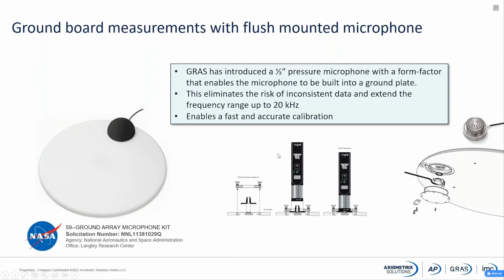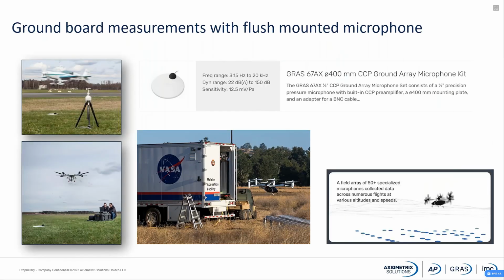What is also a very good advantage is that we have an adapter where you can put it on the microphone directly, and you can do a field verification or a calibration directly on the plate. So we can use the pistonphone or we can use a calibrator on top, and we can do the calibration verification of the measurement chain just before we go live and do the measurement. So everything that they already had in the standards, but was difficult to actually make, we have made into this microphone. And you might ask, is this in operation?